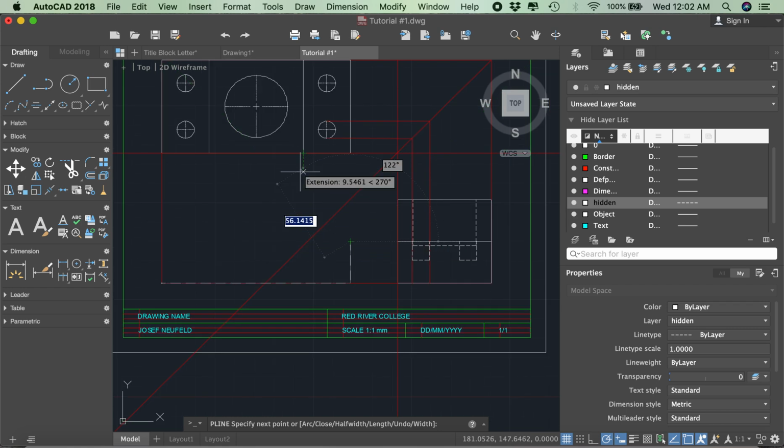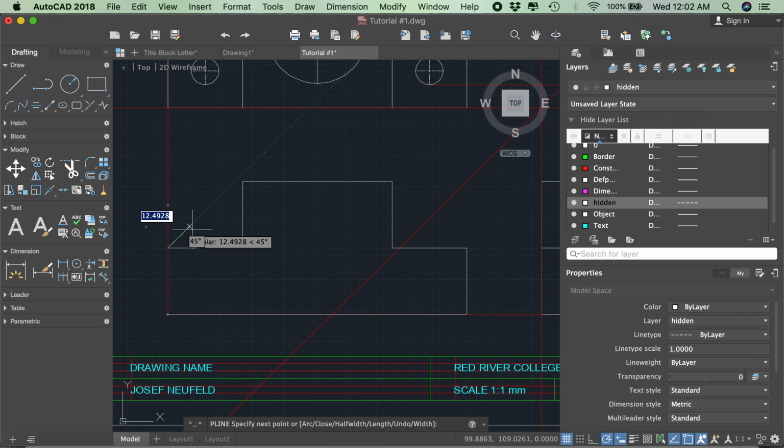Now we can reference off the top view, pulling it down, reference again off the top right side view to get the full height, reference from the top to get the width of the top platform, again off of the side to step down again, and then for the final width here. Rather than clicking to end, if you type in C, it'll close this as one complete item. C will have the line revert back to the original start point.